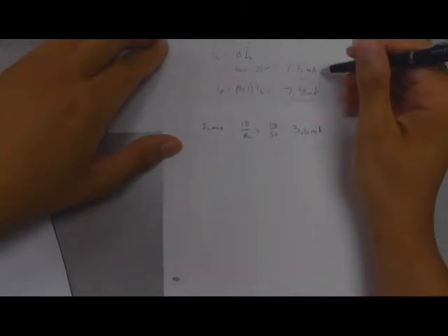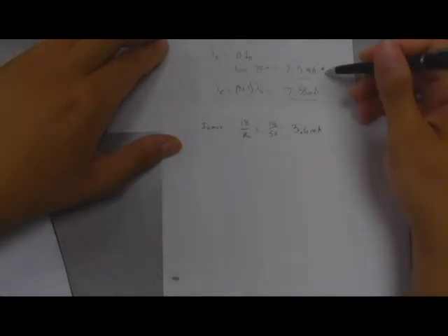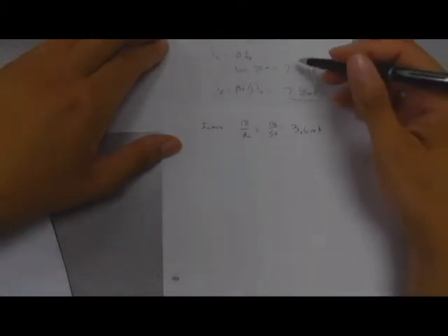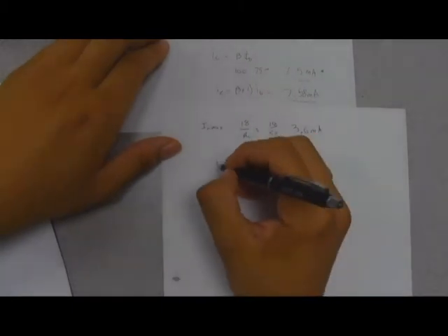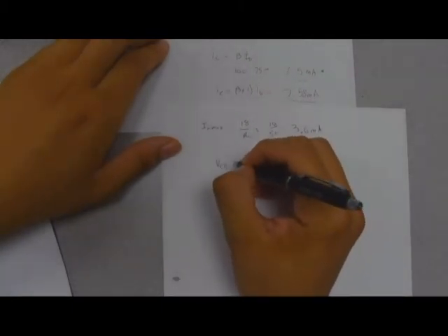Well, if we have 18 volts, we have a maximum of 3.6 milliamps, but we're trying to draw 7.5 milliamps, that means we've saturated this device and that we're not going to be able to draw out this much current. So if we saturated the device, that means that VCE has limited itself to 0.2 volts.